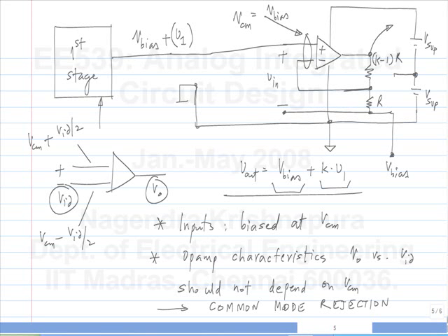No, V-bias is something you choose. So, if you have an op-amp with a certain common mode range, then you have to choose the V-bias within that range. Or I didn't understand your question, I think. Sir, we are having the V-bias from another circuit. Yeah, this we don't have any restriction. Well, okay, the question is if the bias voltage provided by whatever is driving our amplifier is incompatible with our op-amp. Now in that case you can't drive it. That's the only answer, right?